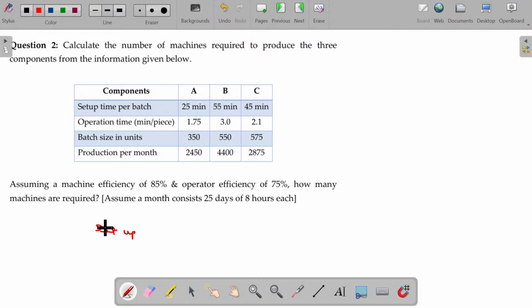Is that clear? So always remember, time requirement for any product manufactured will be calculated based on the setup time also. Once you set up, thereafter you can produce 100 units. First you calculate the setup time, and that should also be taken. When 100 units are manufactured, that is called operation time, and that should also be taken. That's all. Rest of the things are the same. Right.